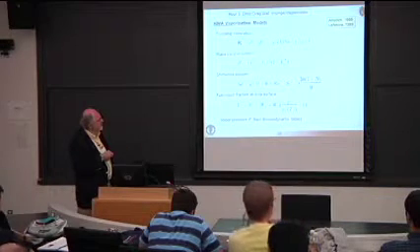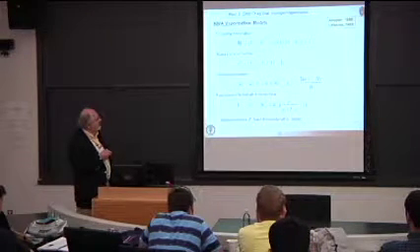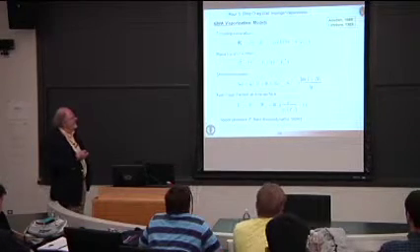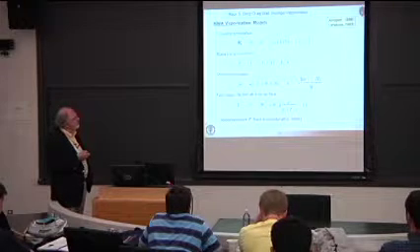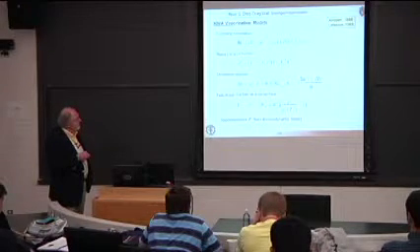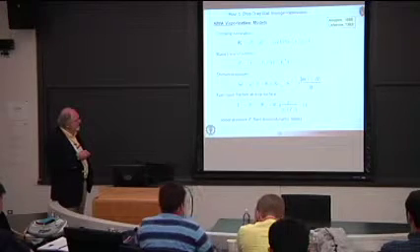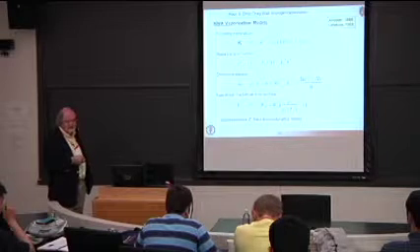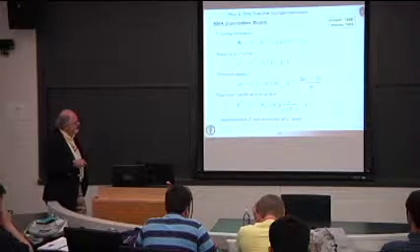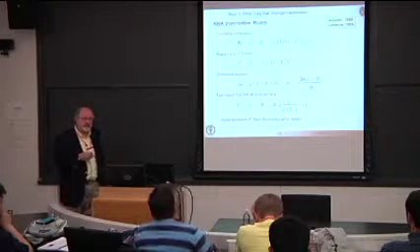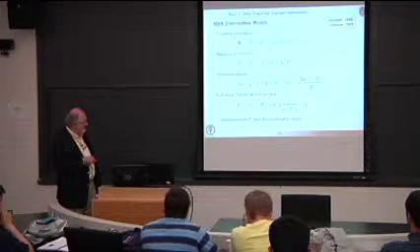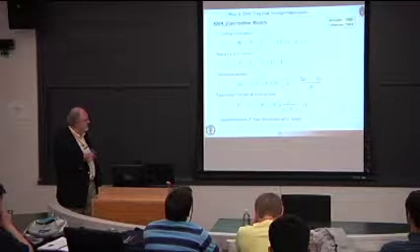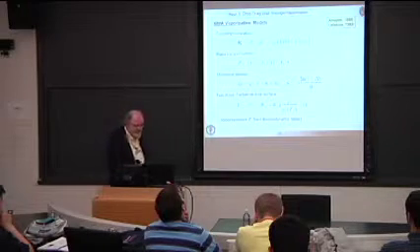So if all this stuff over here is a constant, and we can take this r to this side here, we get r dr/dt is a constant, then we get the D-squared law, right? That's r squared is linearly changing with time. To determine the fuel mass fraction of the drop surface, we need to know the vapor pressure, which is a function of the droplet temperature. And in most codes, it's assumed that the droplet temperature is uniform inside the droplet and all the way to the surface. So if we know that number, we can calculate the vapor pressure that gives us the mass fraction at the surface, and hence we can calculate the vaporization rate.